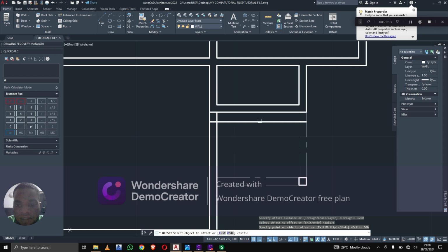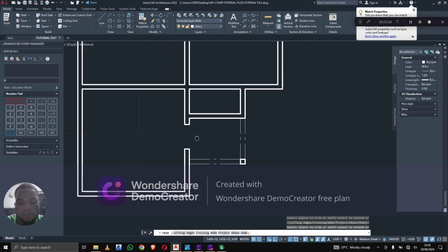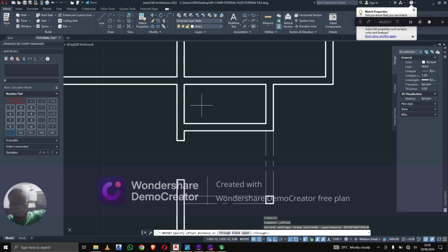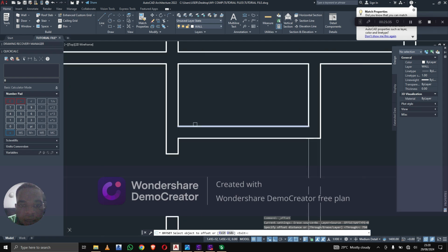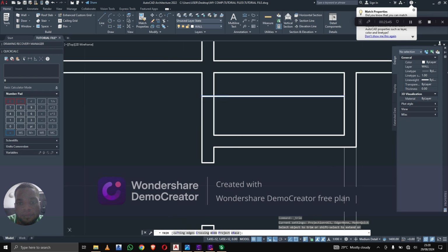So click your trim this excess and cut out the door space. That is my door space. For this toilet, to enter the toilet, you need a door. The toilet door is normally 750 mm. I want the door to be around here. Cut it out. I'm supposed to give this toilet a lobby for it not to be opening into the sitting room directly, but you can't be doing that now. So trim this. This is our entrance.